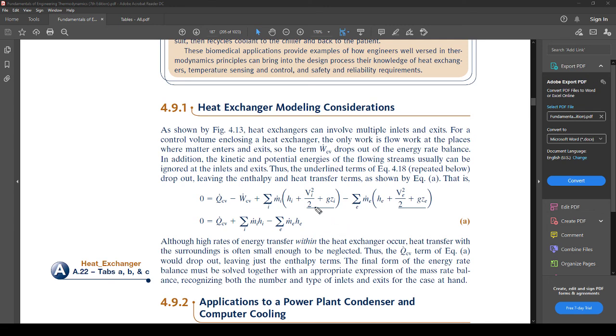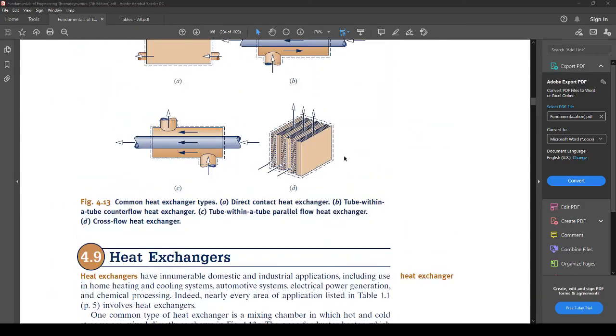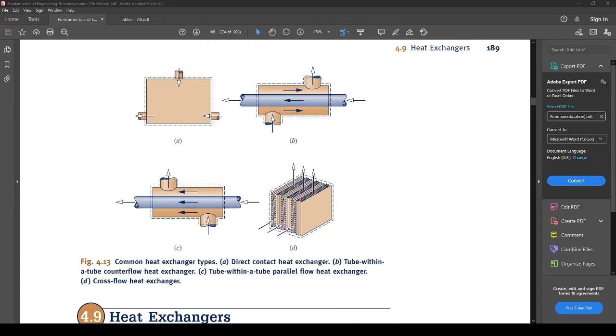And so here's the reason why. When you enter one of these heat exchangers, our goal is to transfer heat, right? So what would be the point of sending this fluid in here going 100 miles an hour when trying to transfer heat? You see, the point is that it would not transfer very much, because remember, heat transfer is a function of mass flow rate, temperature difference, but there's also velocity, right? If there's not enough time for it to even touch the heat or get the heat to conduct into it, it won't ever actually transfer it. So you'll get very little differences.